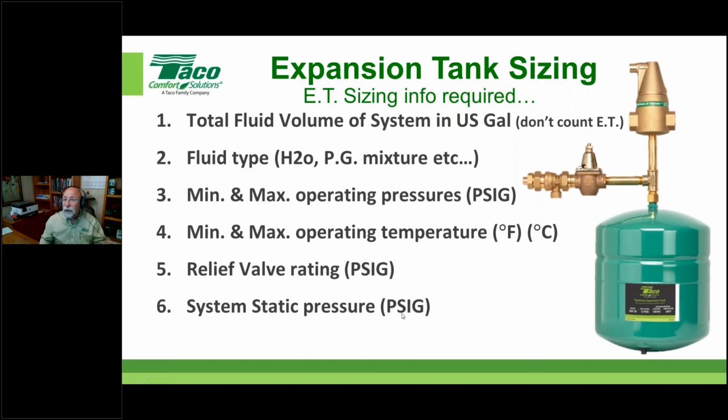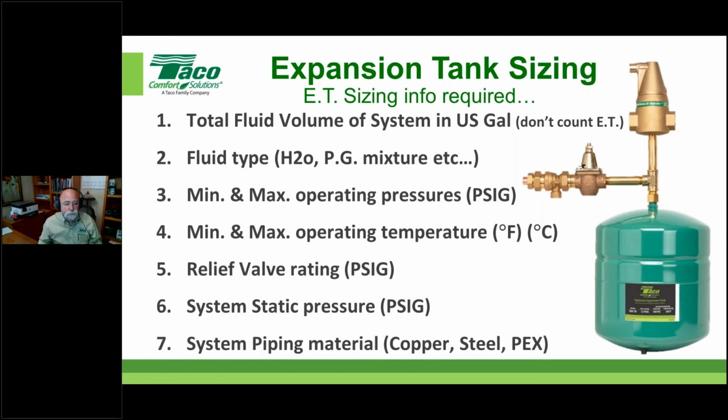Again, we need to know how big the building is in height, because that will change, and it'll have to do with that calculation that we do back here on the expansion tank on the fill, the initial static fill pressure that we put on the system. In a lot of cases this matters, but some software programs don't ask you this.